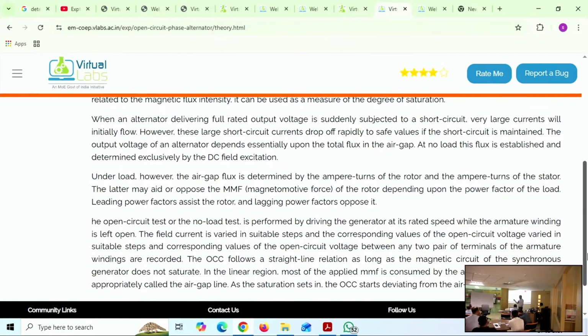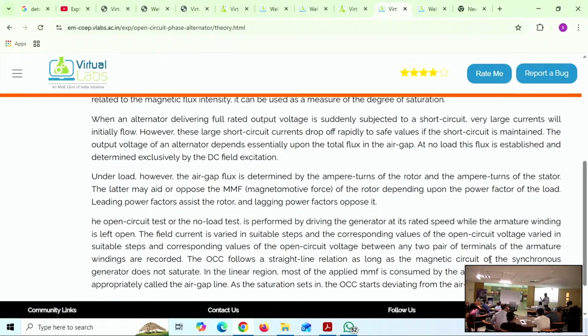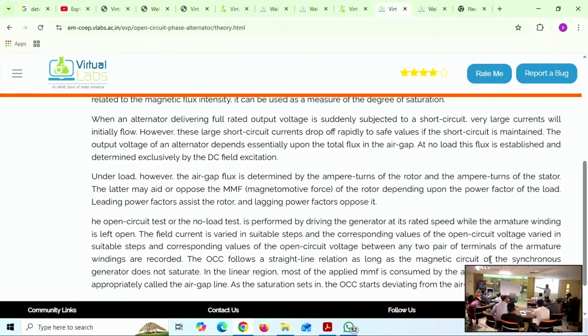There is a starter. He may think that inherently the alternator requires a DC circuit. The alternator needs DC only for the field winding. What we mostly do is use the same DC supply for the shunt motor, the prime mover, and for excitation. This practice poses some risks. It is better if the machine part, the prime mover part, and the excitation part are all isolated, with individual grounding.